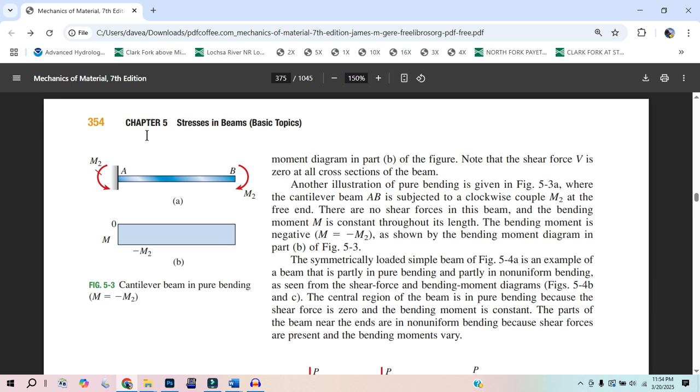If we go back to our beam in outer space and I'm applying this moment over here, this moment is two vertical forces, so there's no resultant force. There's no resultant force causing it to travel across the universe this way. Our beam in outer space just has a downward and upward force, equal in magnitude, opposite in direction, but it is causing a twisting. So I come over here to the reaction.